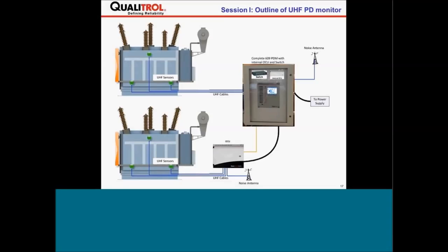We apply external noise sensors through an antenna. This is in case the noise is very severe, external noise is very severe on the site. But in general, because the tank is very enclosed, the noise level in general is very low within a transformer for UHF signals.